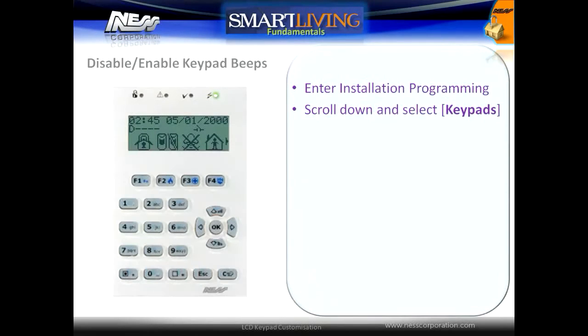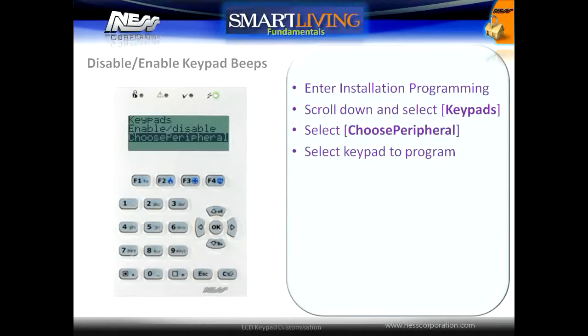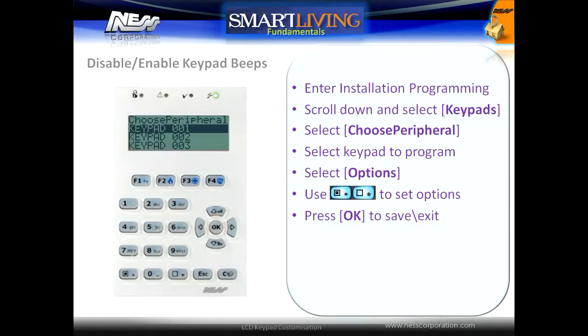To disable entry and exit beeps on a keypad, enter Install Programming Mode, scroll down and select Keypads, select Choose Peripheral, and then select the keypad to program. Select Options and then use the check keys to set the options for entry and exit beeps. Press OK to save.